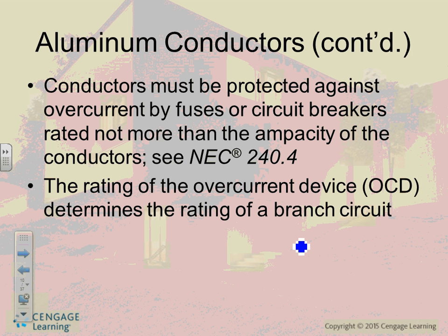So what's their disadvantage is, well, they don't conduct as much current, so you have to have a bigger conductor for the same load. And they expand and contract at a higher rate, so you do have to have preventative maintenance in your building, which a lot of people do. So every year you go torque or you thermal image all the lugs, and the one that's about to get loose, you just torque them. And they put some material, guys, to handle the expansion and contraction too. So that's basically your aluminum versus copper. Utilities use aluminum successfully over the years, guys, outside all the time.